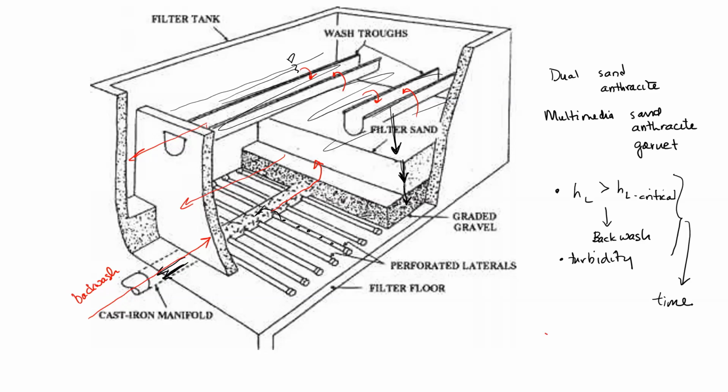This is only half of a filter box. There is a main trough, which is what you see right here, or gullet. And there is a mirror image of this unit on the other side. So always think your filter is always two of these. You will also never have one filter. You'll always have two filters, and that has to do with the hydraulics, because the hydraulics are complicated. So we always put in two filters.